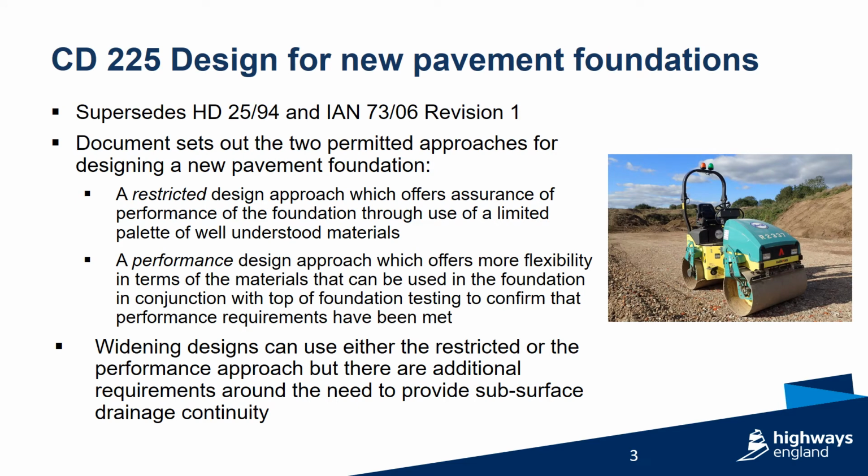CD225 gives two foundation design approaches for new pavement foundations. One, a restricted design approach through use of a limited palette of well understood materials, and two, a performance design approach that provides flexibility in terms of materials that can be used. For this approach, testing at the top of the foundation is needed to confirm that performance requirements have been met.